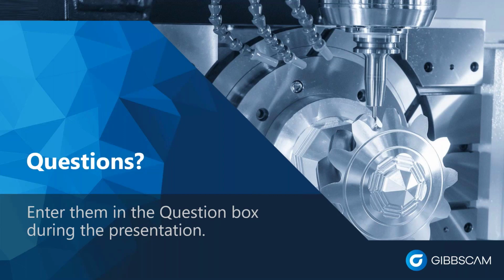In fact, what we're running into more and more is there are customers that only have 3-axis machines or 4-axis machines, but they want to use 5-axis machining strategies. And there are big benefits to this. In a 3-axis environment, you might be able to utilize the side of the tool to do faster machining versus just doing ball end mill point to point over an entire surface. So the short answer is yes, you can use 5-axis machining strategies on non-5-axis parts and features, and there are some really big benefits to that, to tool life and machining time. I don't know if there's anything else you wanted to add to that, Stephen. I could not. That was very complete.